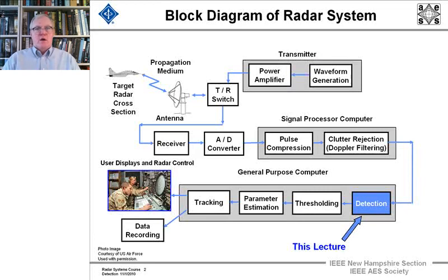techniques within the radar, some of which will have to do with the antenna and how we place nulls optimally in the antenna side lobe pattern, and others on how we do signal processing to reject backgrounds that aren't noise-like but are colored, that have a Doppler spectrum that's not uniform.